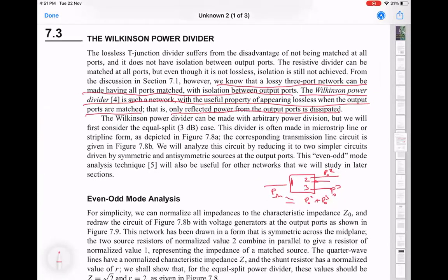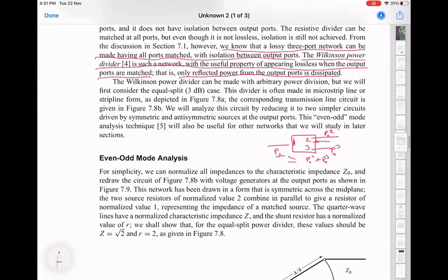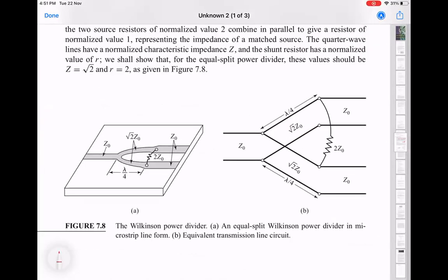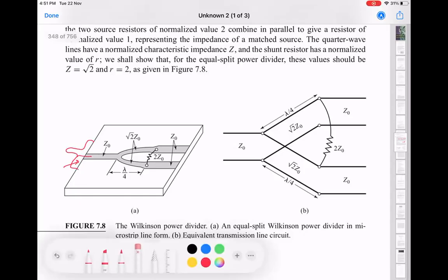Okay. So this here is the actual circuit. On the left is shown how it would be done in a microstrip geometry. So you have a feed line. If I had extended this, I would have had my connector here and some kind of launch coming in, connecting it. So the feed line is 50 ohms in all three ports, right?